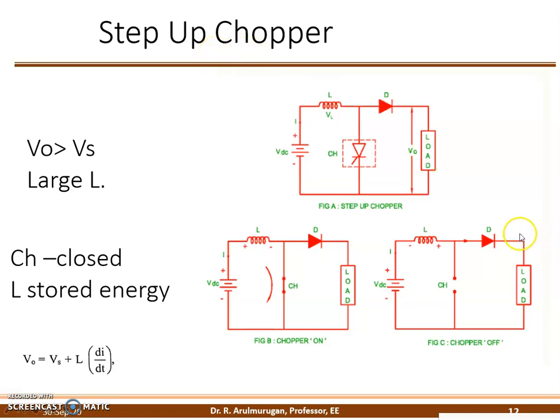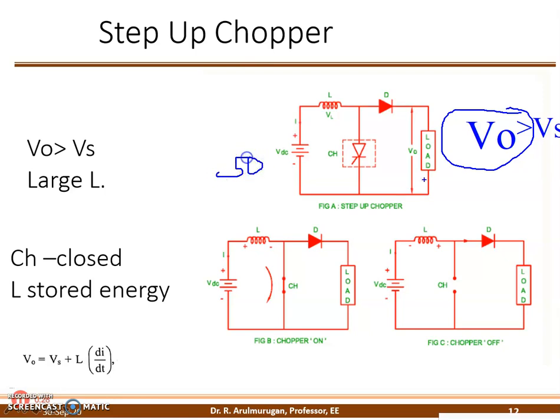What is the boost converter? I am going to repeat. Output voltage is greater than input voltage, so V naught is greater than Vs. That is called a boost converter. Output voltage is greater than the input voltage. So here 50 volts input means output is 100 volts.